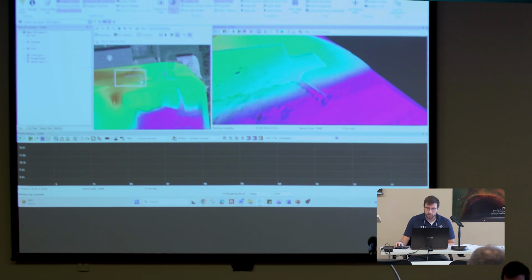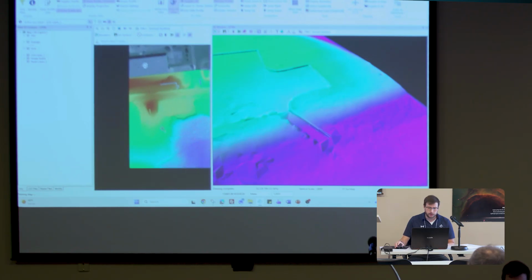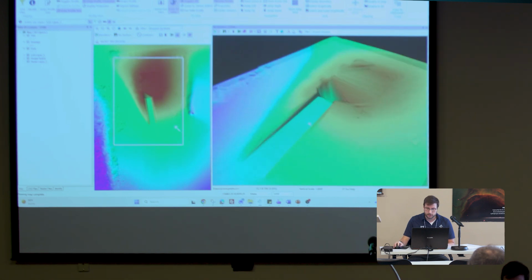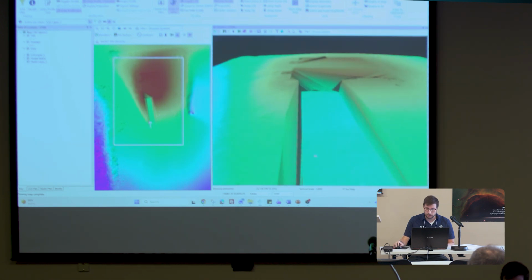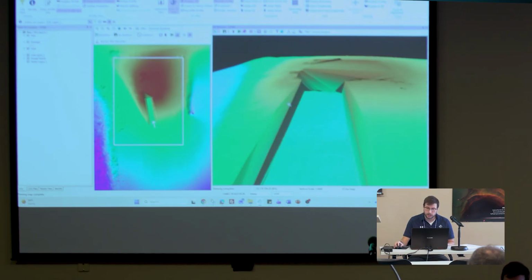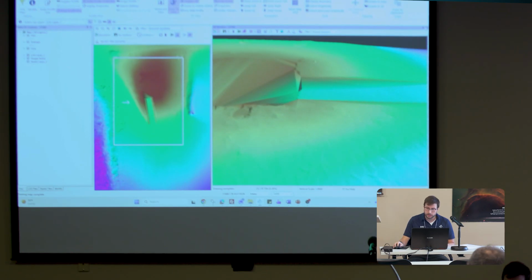And so we can do that in the other 2 locations as well. I'm just going to do that real quick. I'm going to go and turn the profile view off. And then I'll zoom into our wall over here at the bottom, do the same thing. Just doing a little bit of a sanity check here, just a little bit of analysis to make sure that before I spend time producing my DEM, DTM, that the data isn't looking off, and just making sure the breakline's enforced the way we want.